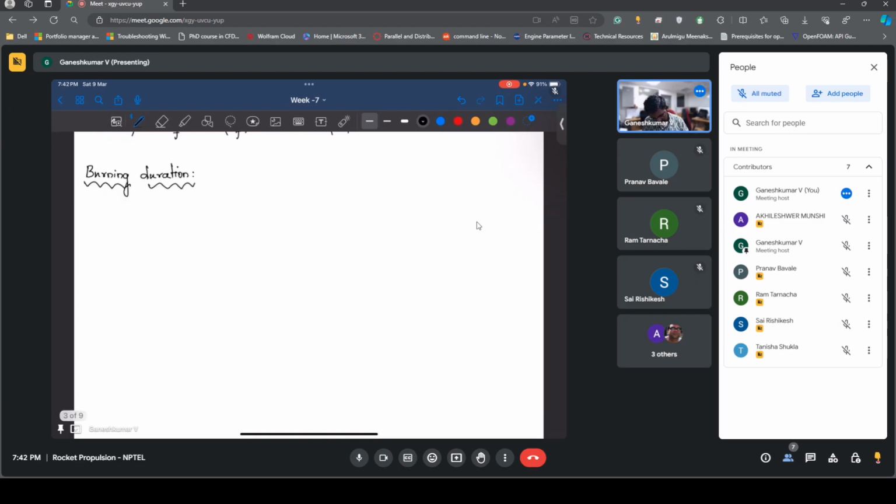So basically, to begin with, you can use the RB. RB is nothing but the burning rate, which is dr by dt, the rate at which the radius is regressing. This is a hollow cylinder, so it might be easier, but you should be a little careful while doing it for other geometrical sections. That's why I'm going a little slow here. We can even simply use the formulas which the professor derived, but I wanted to take some time here.